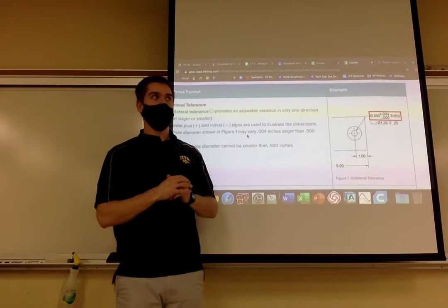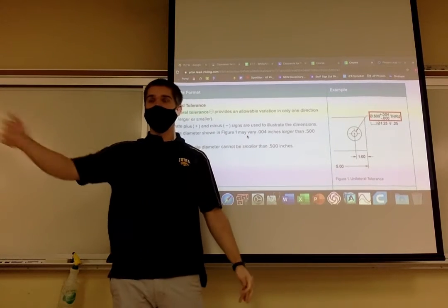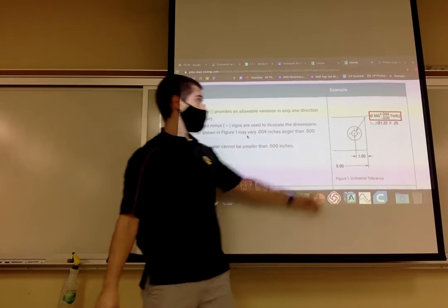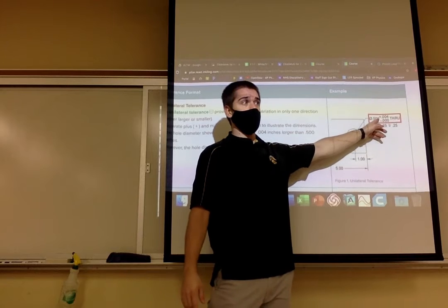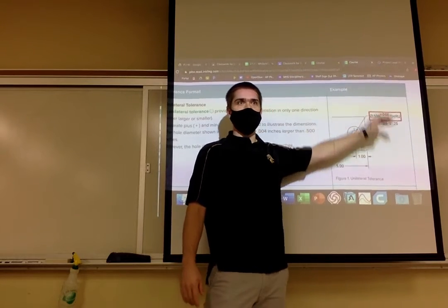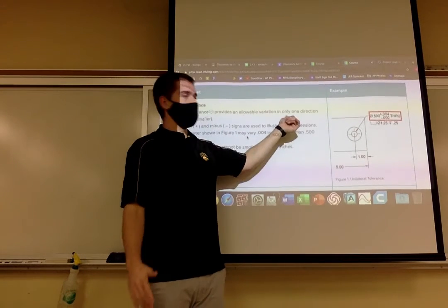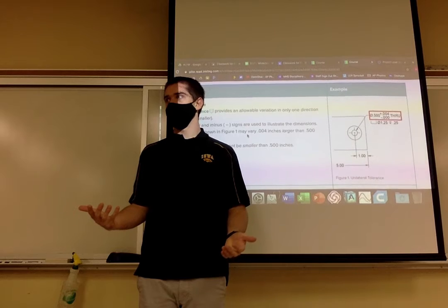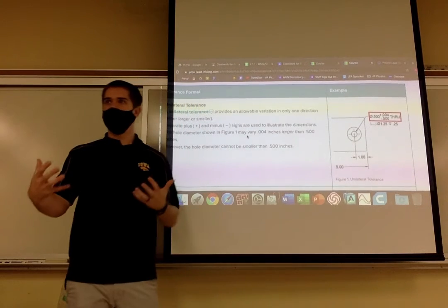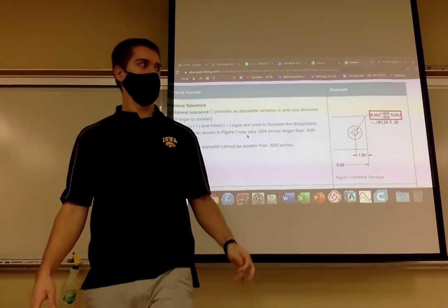A hole that's 0.499999 inches is not acceptable. Now, I could have my hole be 0.501, because I'm giving you some tolerance on the positive side. The tolerance, the room for error, is only in one direction. That's a unilateral tolerance. That should make sense, right? I only give you room for error in one direction.